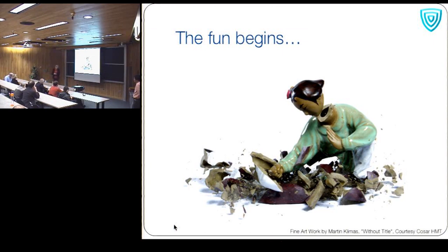So you have a good point. We do have unstable crack growth, but this big flaw is undergoing unstable crack growth, but it's rate limited. And because of that rate limitation, it's allowing these other flaws to start taking off too. And you see the damage as a function of flaw size. For the static case, it's all in the big cracks.